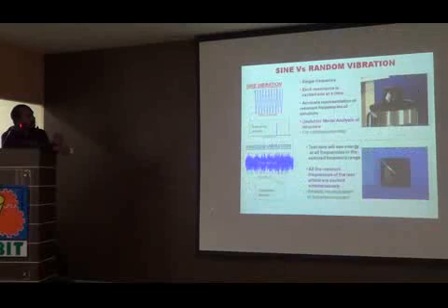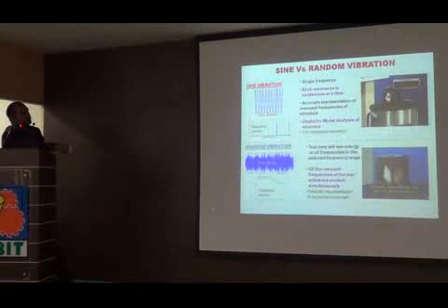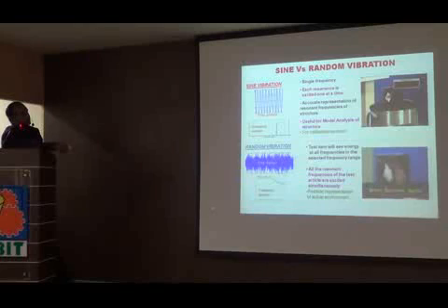These I will explain. Now let us see what vibrations we do. We do something called sine vibration, and something called random vibration. In sine, what we mean is only one frequency is exciting. You can see in random here, both are excited at the same time. For example, if I take one component having one frequency 22 and another having 33, if I excite with sine, only one will be excited, either 22 or 33 at a time,